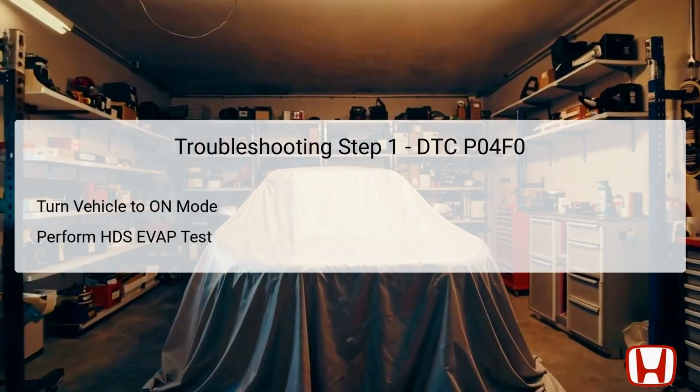Performing this function test is critical, as it provides the technician with a preliminary overview of the EVAP system's operational status. The HDS will run a series of checks, analyzing the components involved in the evaporation system, and will help to identify any electrical or operational issues within the system. Adequate knowledge of the HDS functionality is essential for effective diagnostics and to ensure the test results are interpreted correctly.